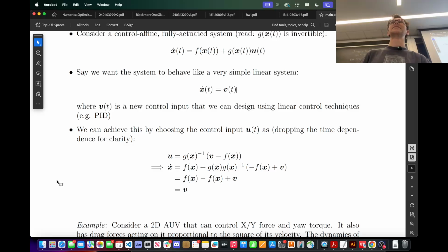Getting back to this optimal control stuff, if you wanted to coordinate your arm movement with the movement of the sub, you would want to do that in a joint type optimization. If I know that I need to be here to pick up this water bottle, I might want to design a trajectory that knows the arm can only move in certain ways, say it's a 4-bar and can only move like this, and we want to come down and not smack the bottle on the top. Then you have to be a lot smarter about how you generate the desired trajectory. But for actually controlling the sub mechanisms, like the marker dropper or the torpedo launcher or any arms, it's usually just a servo.